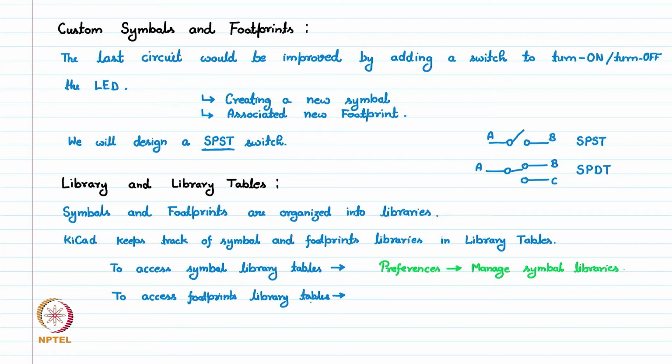And to access the footprint library table, you can go to Preferences and Manage Footprint Libraries.